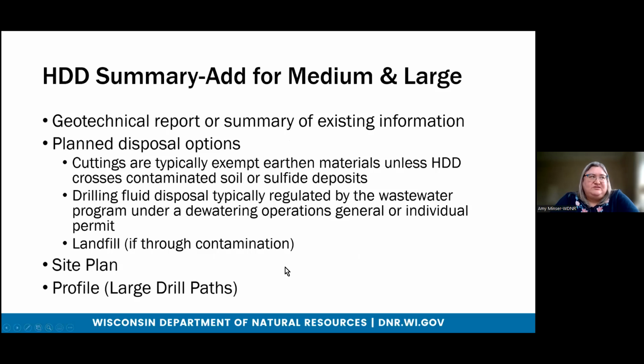For medium and large horizontal directional drill paths, we'd like to see the geotechnical report. We'd like to know what disposal options the contractor will be given as far as what they're going to do with the drill fluid and cuttings. And there's some notes here on this slide from conversations with our wastewater and waste programs.